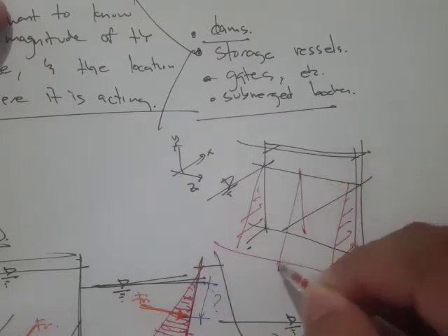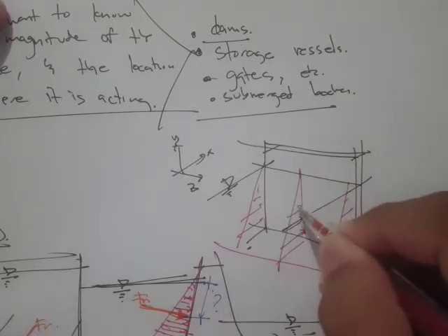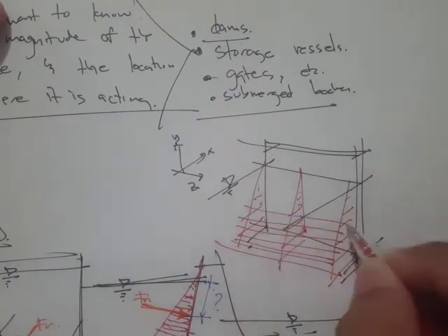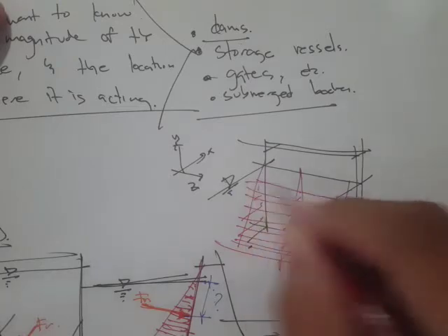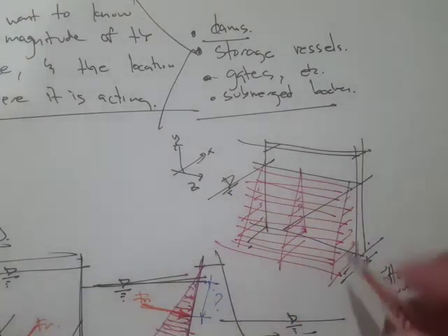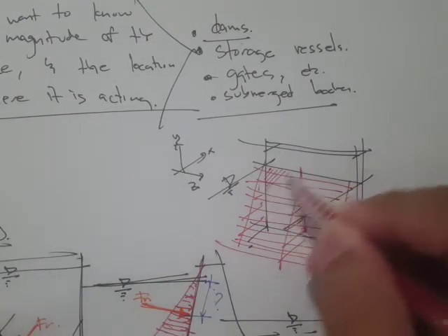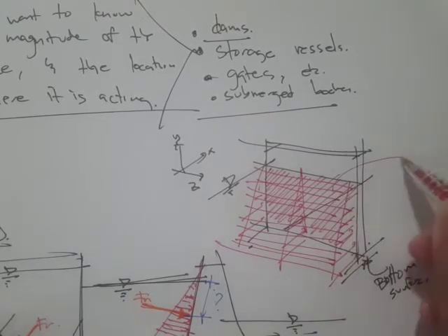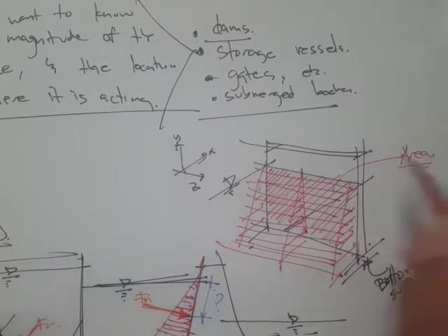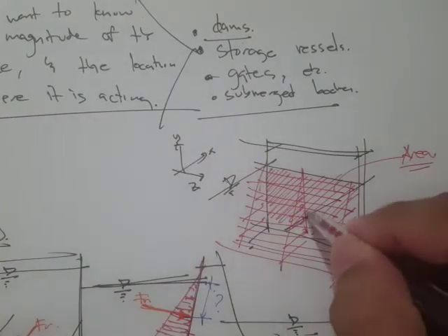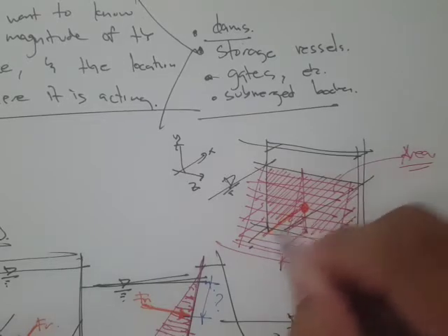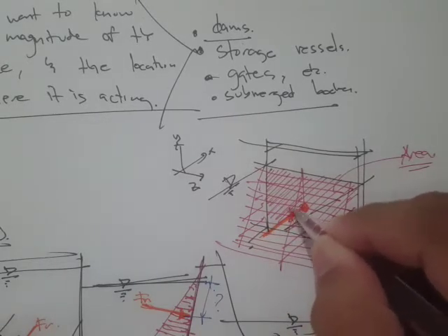This pressure profile is actually three-dimensional, acting on the area, and this is the area concerned. So if we want to consider the resultant force, this resultant force will act at the centroid.